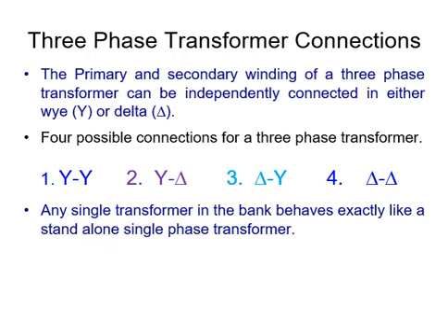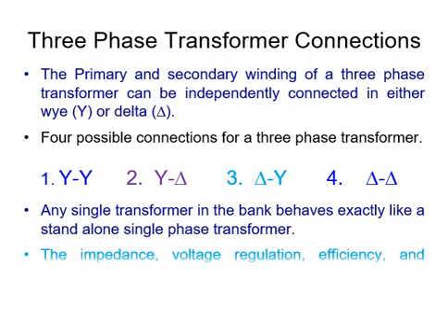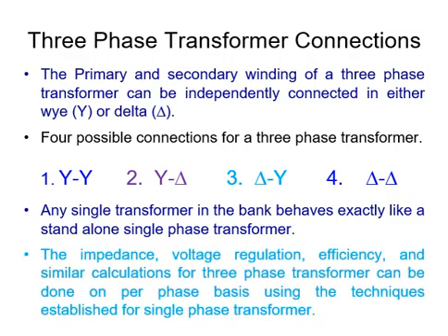Any single transformer in the bank behaves exactly like a standalone single-phase transformer. The impedance, voltage regulation, efficiency and similar calculations for three-phase transformers can be done on a per-phase basis using the techniques established for single-phase transformers.